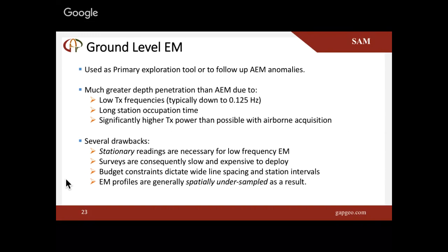Ground level EM is great. We can have much lower transmit frequencies to get better depth penetration. We've got the ability to have longer station occupation time, so better quality data because we can stack longer. And you get higher transmitter power than possible with an airborne system, because we have the ability to have a much larger generator and a much larger loop than you can actually deploy from a helicopter.